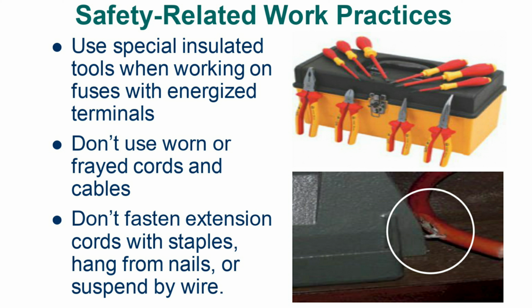Safety-related work practices: use special insulated tools when working on fuses with energized terminals. Don't use worn or frayed cords and cables. Don't fasten extension cords with staples, hang them from nails, or suspend them by wire.